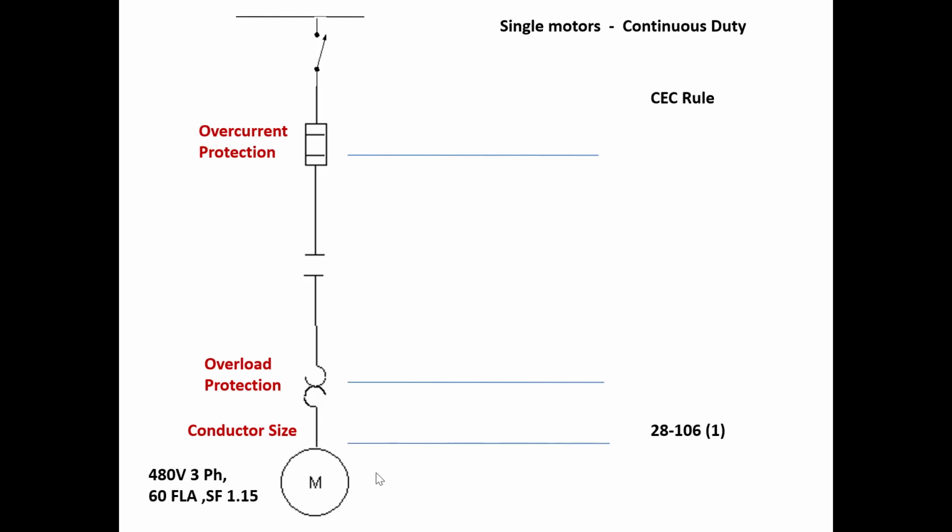So we take our FLA of 60 amps times 125%, and we get 75 amps here, and we go to Table 2 and size the conductor, and we're sizing based on 75 degree. I don't have that written; when I do it on the board, I would write 75 degree termination temperature. So then we're going to Table 2, under the 75 degree column, and we pick a wire based on that. So we need number 4s being fed down to this motor.